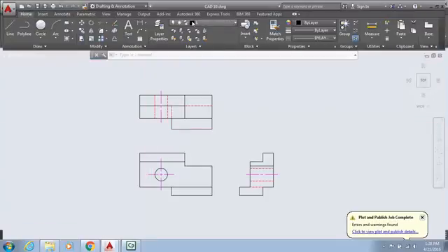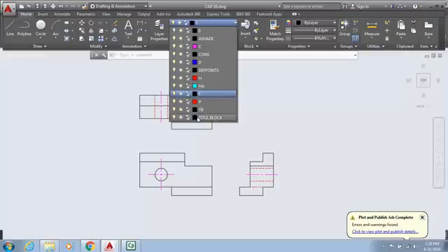drawings. I still like to use the layer. You still have all your layers. Remember, every time you create a new drawing, you got to open up the seed file, the seed.dwg, and then do a save as. The seed file has all the attributes, the layers, the dimension properties set up in it, so you don't have to create that. If you're making a drawing and you don't have all these layers showing, you're not opening up the seed file. Okay? And you need to do that so you can have the different layers.